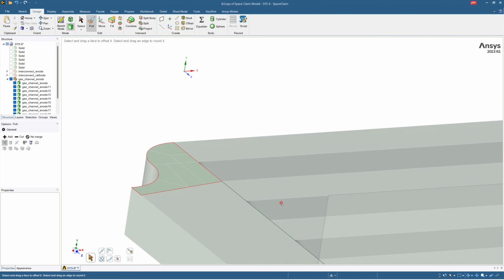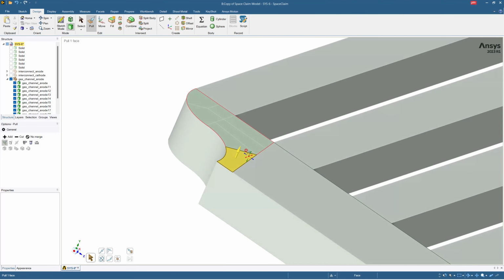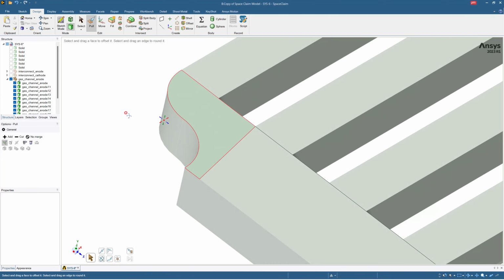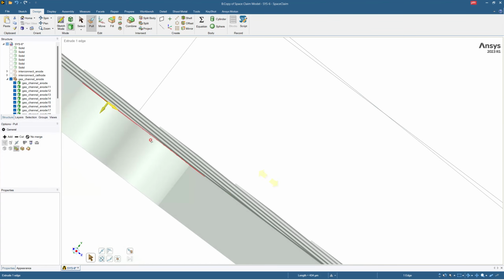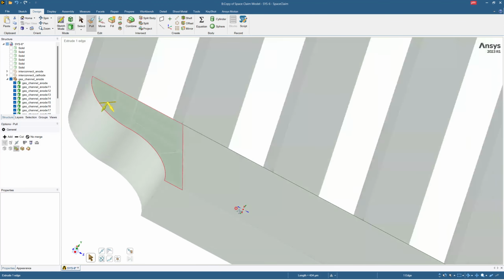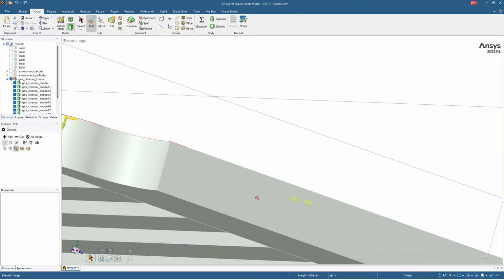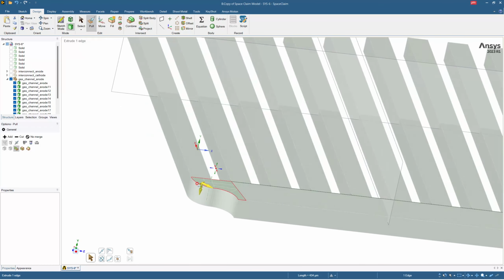So in order to make these surfaces, we should extrude them. We don't want to extrude the face, we need to extrude the edge. So we'll select this edge, and carefully orienting it is also really important. Yes, it is better. So now every edge is also visible, and we can select this arrow to extrude this plane.